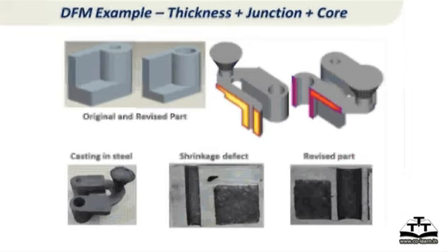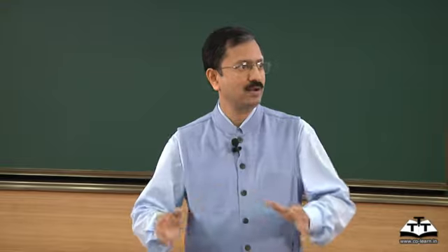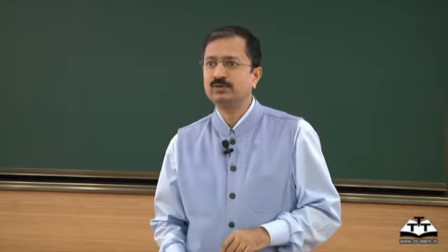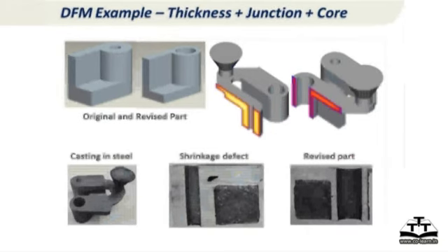And what we did, just to prove our point, we made both the castings, both the two different designs, in the same mold with a same common gating system. So conditions of metal and pouring and everything are exactly the same. You can't say we have cheated. By doing that, and it's made in steel here, you can clearly see the thickness, the bottom now becomes the top here, in the bottom two pictures.